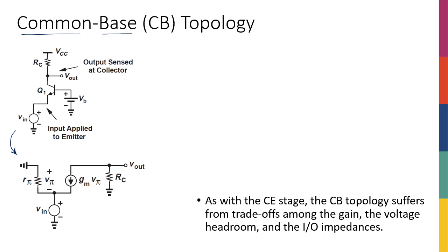So this VB here is really a bias voltage, right? A bias voltage is DC, and the symbol suggests the same thing. It's a battery, so you can imagine that it could be, for example, 1 volt. Now, how about the Vin? We know that it could be a combination of DC plus AC.